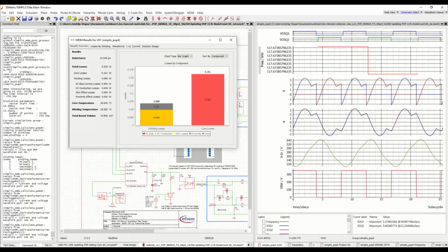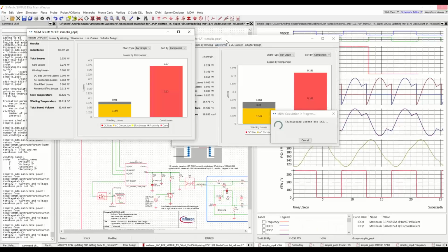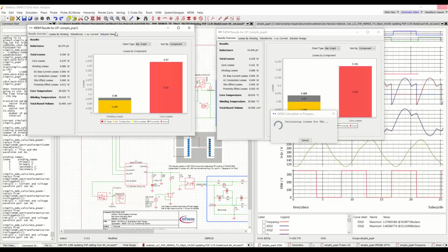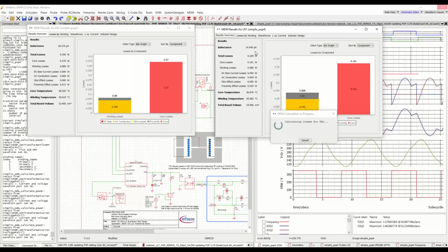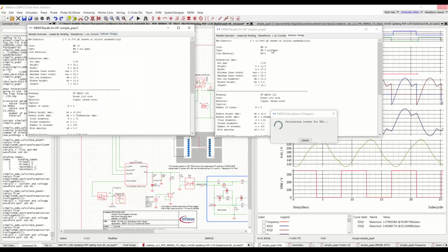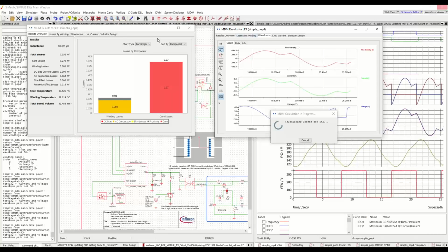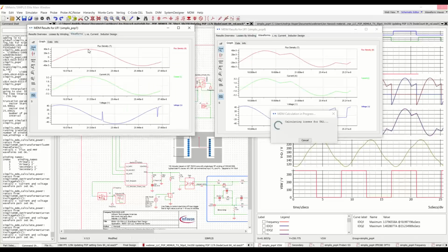Now, we can look first at the inductor. So that was that operating point previously. The inductance has been decreased a bit by going to a slightly smaller core, from an RM14 to an RM12. And what we got are smaller core losses. That's because the flux density peak stayed approximately the same, but with a smaller core volume, we have less losses overall.